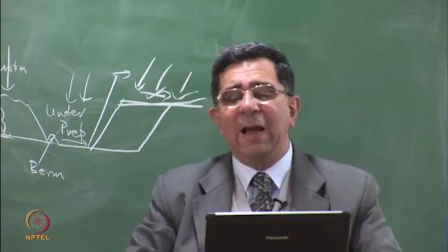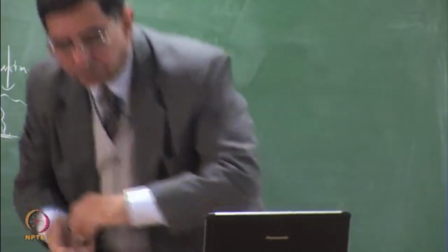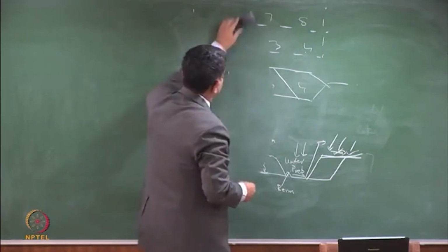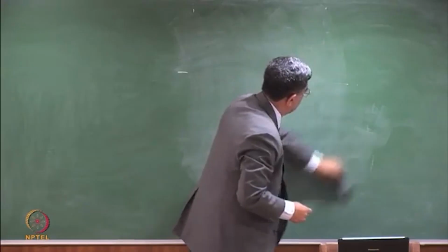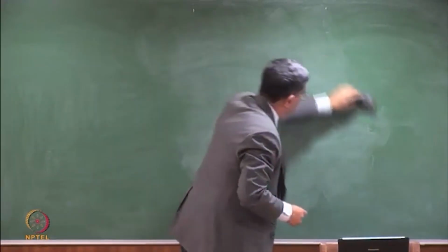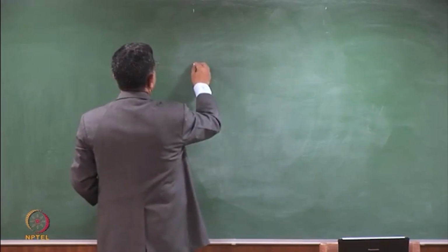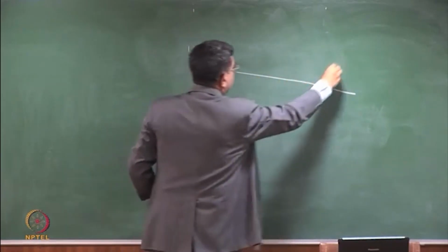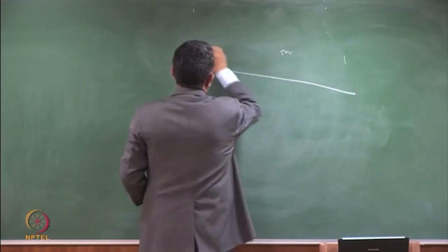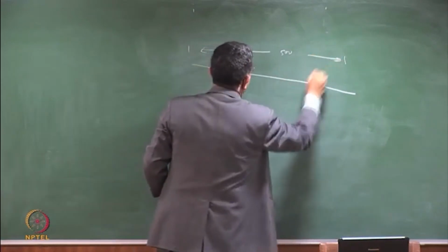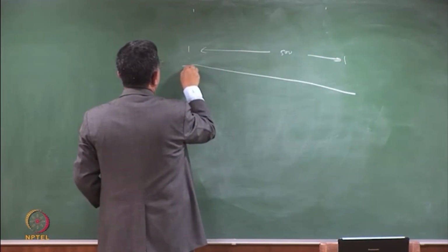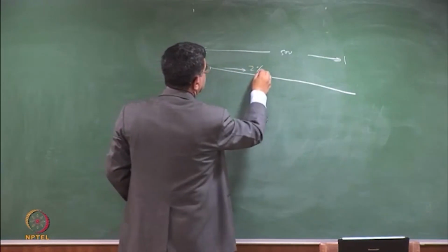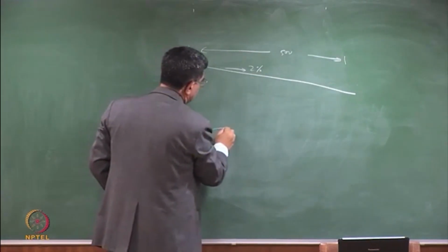So then you see what will happen is when the width is very large, if this is 500 meters, then a 2% slope will give you a 10 meter drop. So in such cases, the base of a landfill starts to look like this.